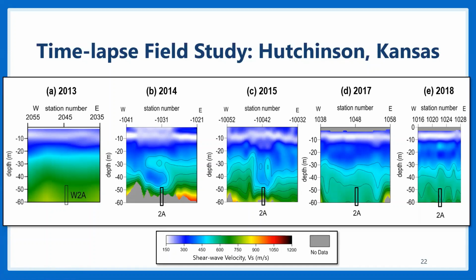And while it's not the focus of this talk, we used those nearby trains I mentioned earlier as our passive seismic source, because we needed to achieve a lot of depth at this area in particular, because if you remember, the depth to salt was about 80 meters, which is quite hard to achieve with just an active source. So we used passive seismic sources. So in this first year, 2013, we identified this as a baseline study.